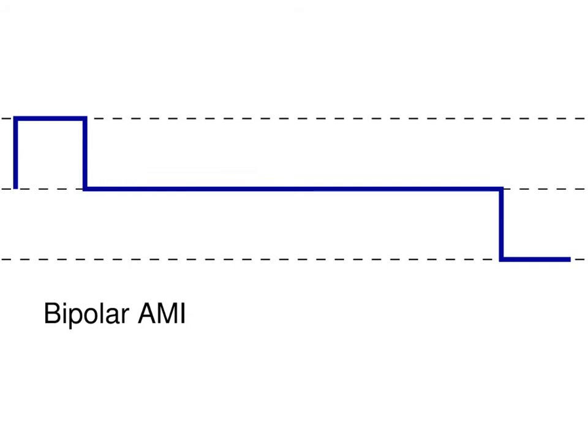Visually you cannot see it, obviously, since I've removed the lines. So what the receiver does is measure from here: our signal changed. That means there's a new bit, because by definition, if the level changes, there must be a new bit. Then 2 milliseconds later, but again, if the clock at the receiver is not accurate, where is the 2 milliseconds? Is it here or here?